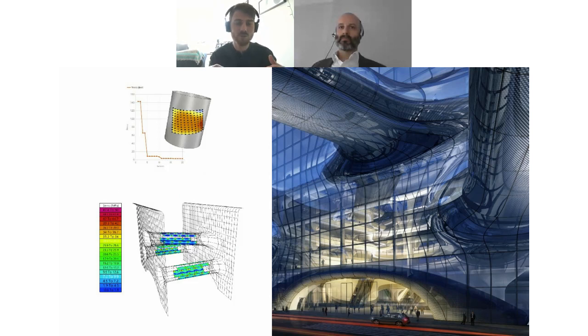So behind the scenes of this script, we've got 2 really important processes or analyses that are carried out. The first one's illustrated by the top image on the screen, which is cylinder fitting. For each panel, we try and find the best fit cylinder for that panel, the cylinder that best approximates the geometry. And we have a custom script which optimizes the cylinder, iteratively tweaking the cylinder and finding the best match, so that the difference between the panel and the cylinder is minimized. The second important process that runs in this script is the cold bending analysis.